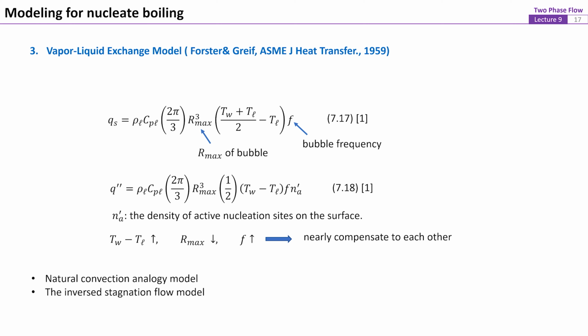When the bubble releases or collapses, the motion and the vacancy left behind the bubble draw cold liquid into contact with the hot surface. Each repeated cycle contributes to an exchange of thermal energy between fluid at the average temperature of Tw and Tl, and fluid at temperature Tl.